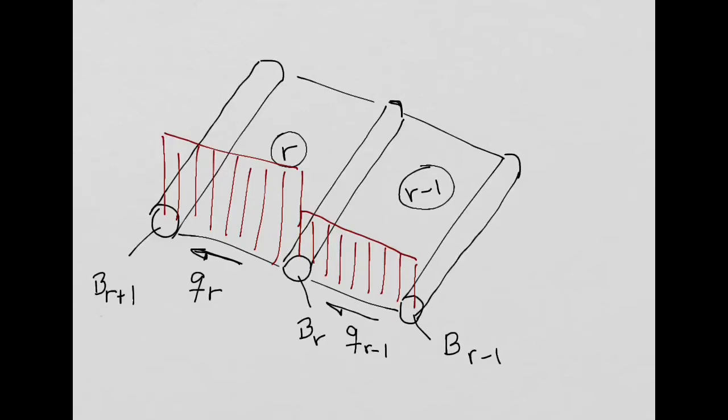Okay, so that is one advantage of these idealized structures. We have constant shear flows in the skins. The only thing we need to basically derive now or calculate is what happens to the shear flow when I cross the boom. And that's what I propose to do with you now, to study that.